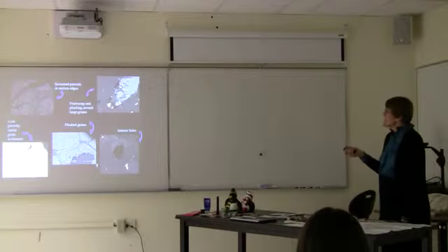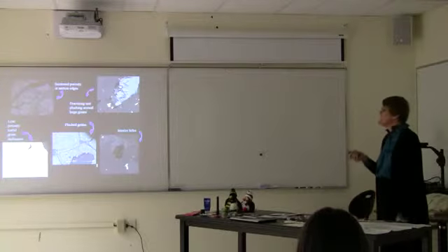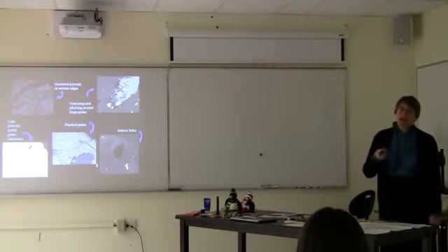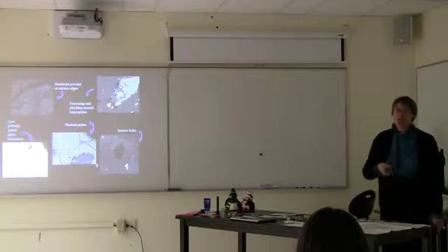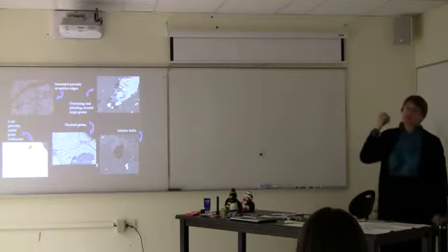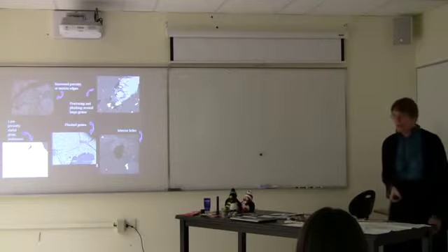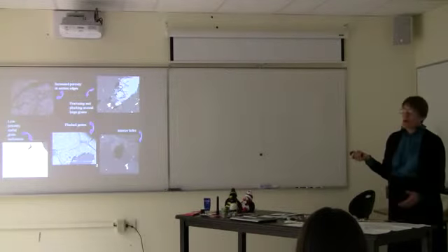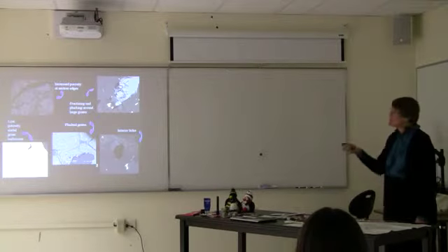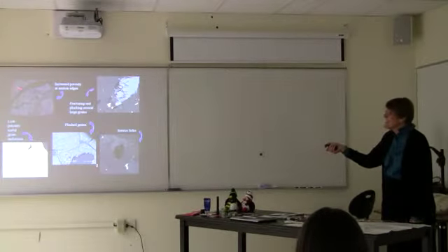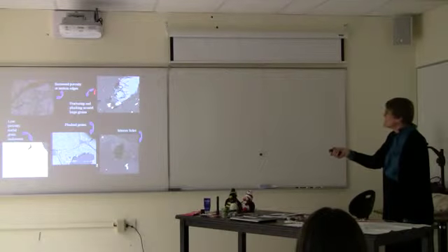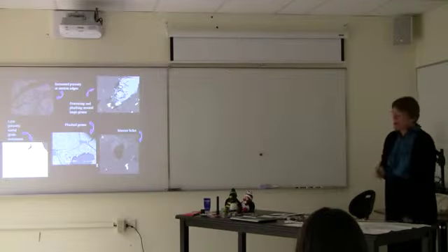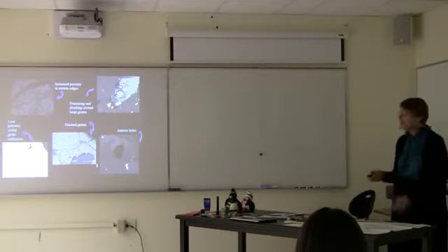In addition, in doing all these observations, there's a variety of problems that crop up. People tend to say, the numbers you get off your thin section, we don't believe, because when you prepare the thin section, you damage it, you remove porosity, you add porosity, and it's just no good. And I say, okay, I've been doing this for 15 years. I've learned to recognize that when you do it at the edge of the sample, you tend to get damage around the edges, which increases the porosity, so I avoid the edges of the thin section. I can look at this and say that is plucking from the grain. I'm not going to count that as porosity. I know what it looks like.